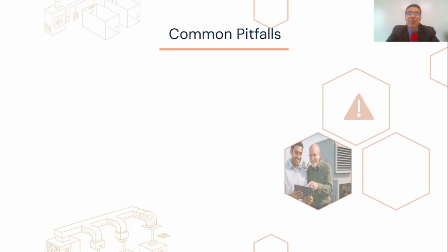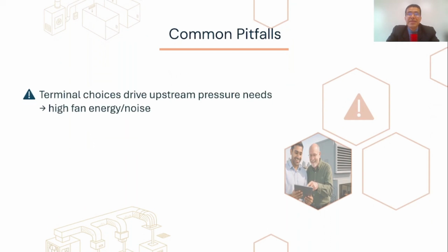Let's talk about common pitfalls in these designs. Terminal choices drive upstream pressure needs. For example, induction devices require explicit duct pressure.